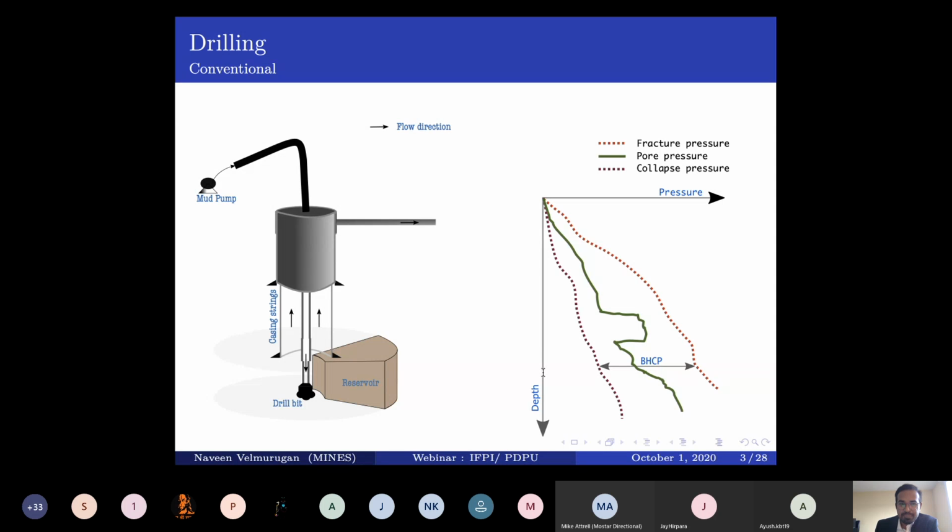What happens is, if you calculate that particular pressure and engineer your density of the mud, when you start the pump, there is an additional friction that acts against the bottom, and you might easily fracture the open formation. So you always have to keep in mind the frictional forces that are acting. The bottom hole circulating pressure is the pressure that you will encounter at the bottom of the wellbore when you circulate the drilling mud, which is slightly higher than when your mud is not circulating.